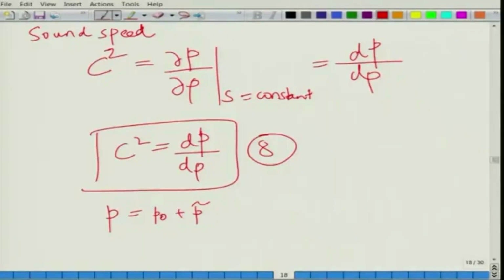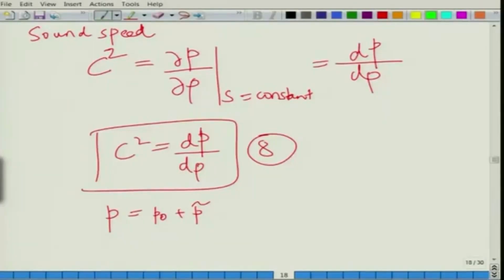The noise, that is the disturbances that are created by the device, they are hitting your eardrum, and that is what is causing the sensation of sound. So, it is basically this P tilde that we are after. This is what we are interested in acoustics, and as you can appreciate, when you do this linearization, we just begin the process of linearization. Obviously, a lot of things have to be done in the momentum and continuity equations; we just begin. So, P tilde is your acoustic pressure, and that is what we are going to relate to small changes in density, which is given by delta rho, or you can write this as rho tilde, which is nothing but total density minus the ambient density, rho naught.